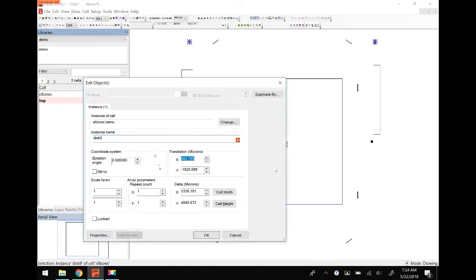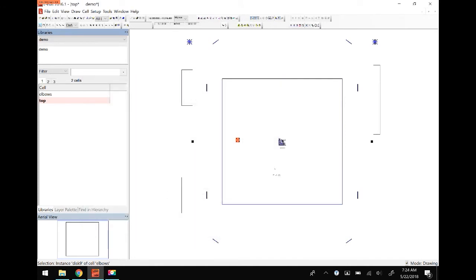I'm going to make sure that that's centered at 0, 0. But you can see here that this data is very small relative to the size of everything. The reticle data is laid out on reticle scale. So that means that what's printed here is ready to go to a printer, to be printed at a 1-to-1 scale. My device data, I wrote to be scaled at wafer scale, device scale. This is the size that I want to have printed on the wafer, not the size that I want to have printed on the reticle.